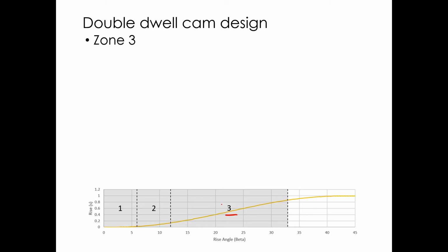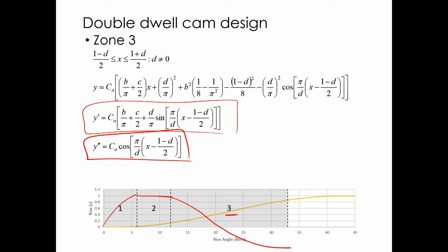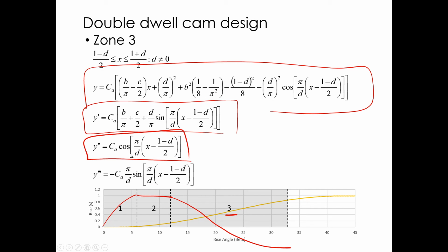Now in this phase, for the acceleration it was going to be this constant. Here we need this sinusoidal ramp like this, so the acceleration is going to look sinusoidal. When I look at the acceleration, actually it's a cosine function, but then to integrate it and get the boundary conditions to line up, it starts to get a little messy for normalized velocity, and then it gets real messy here for normalized position. And then jerk is just going to be another, cosine becomes sine with some constants, not a big change.